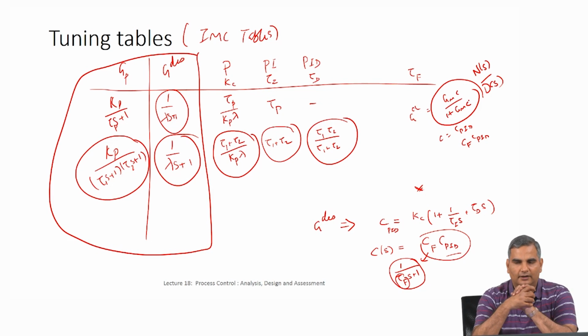So that is what we understood at that point. And then we said, okay, when we talk about this control, what is the structure of the controller? Then I introduced the notion of PID control. P controller is a proportional controller where you are saying the changes to the manipulated variable that I am going to make are going to be directly proportional to the amount of error I have.